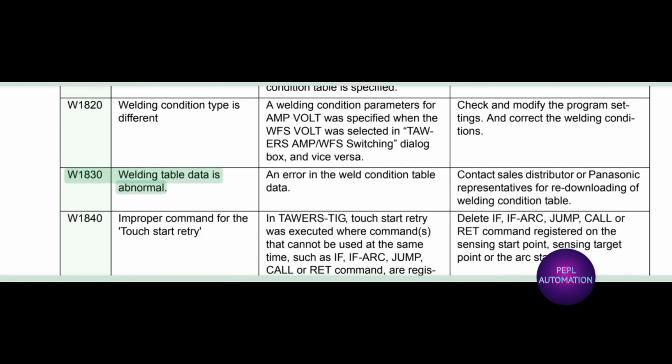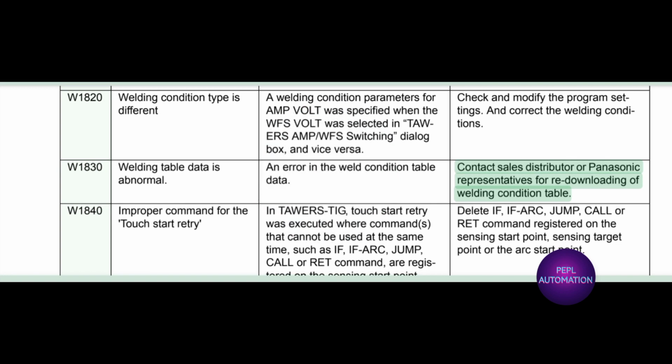W1830 welding table data is abnormal. An error in the weld condition table data. Contact sales distributor or Panasonic representatives for re-downloading of welding condition table.